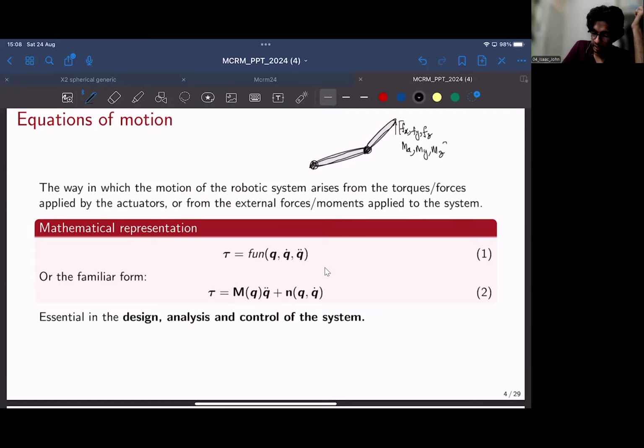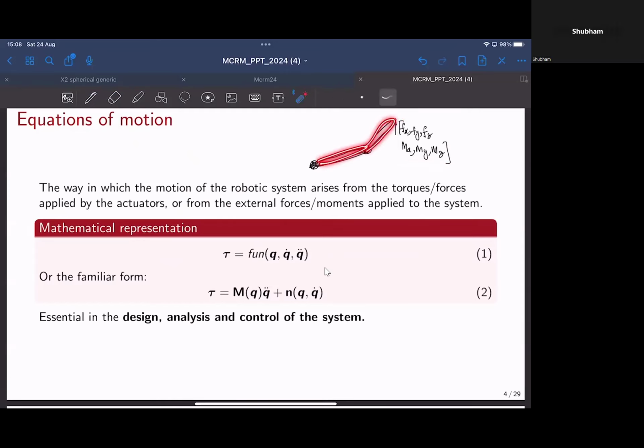So what I have considered is a generalized case. In the case of a planar manipulator like a 2R robot, you need not consider all the 6 variables. You only need to consider the planar coordinates, probably Fx, Fy, and Mz. So just to give a general idea, the forces involved for a robot are the forces acting on the payload, external loads.